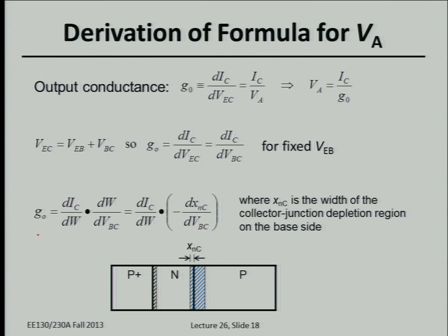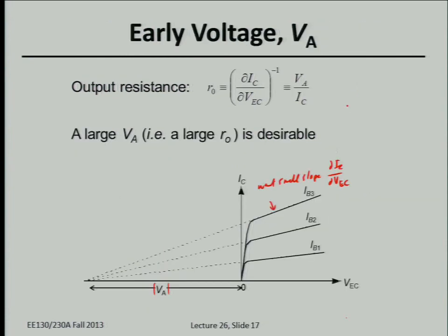From the previous slide, we can come back to this on the next slide, the early voltage is determined like this because of where these curves start to fall down. That's when the IC starts to fall down, when you start to forward bias the collector junction, right? If you forward bias the collector junction, you're injecting holes in the opposite direction, counterproductively.